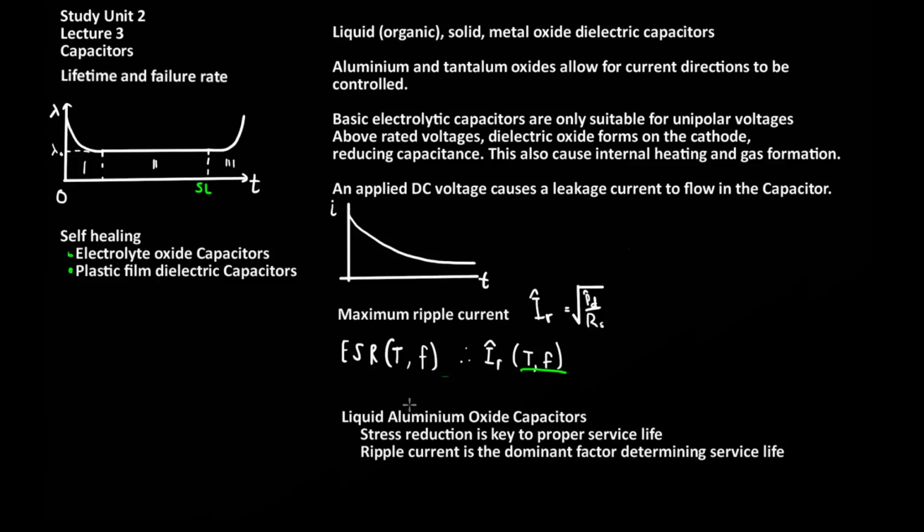In general, solid capacitor types have a high capacitance per unit volume because of a high permittivity present in the tantalum used in these solid capacitors. Solid type capacitors are also more resilient to variations caused by temperature. And finally, a solid electrolyte is stable and won't evaporate with time, as is the case for a liquid electrolyte.